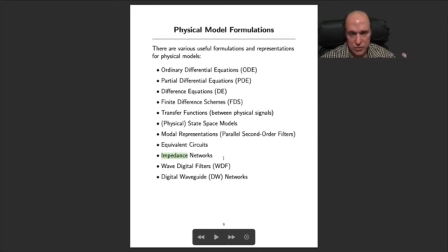It's like taking the Laplace transform of everything, and in the differential equation space, it turns the differential equation into an algebraic equation. So your ordinary differential equation just becomes a polynomial in S for the analog, continuous time case, and it becomes a polynomial in Z for discrete time, and those are a lot easier to work with.